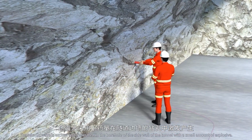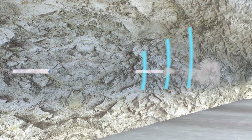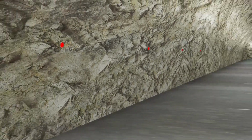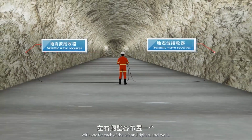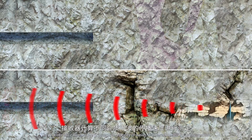The seismic wave is excited and generated in the borehole of the side wall of the tunnel with a small amount of explosive. The excitation holes are arranged along a straight line on one side of the tunnel wall. The receiver of the seismic wave is also placed in the hole, with one for each of the left and right tunnel walls. In case of any groundwater, karst caves, faults, etc. in the radiation range of seismic waves, there will be reflection, refraction, etc. The receiver will calculate the propagation velocity of waves in different media for measurement.